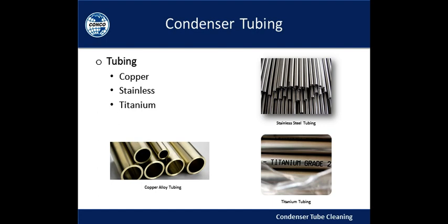And then there is the titanium tubing, which we have seen quite more frequently over the last 15 or 20 years, that provides good heat transfer characteristics. It also does not corrode, and it has a very smooth surface.